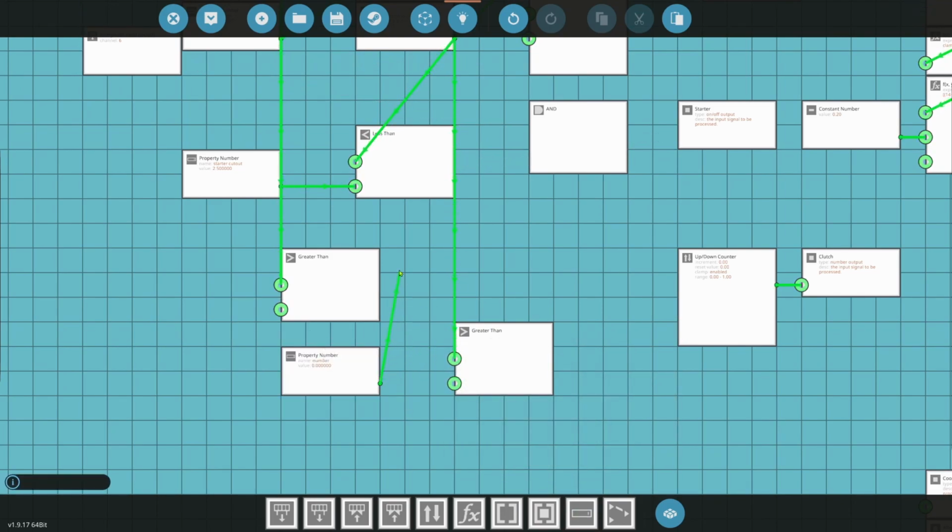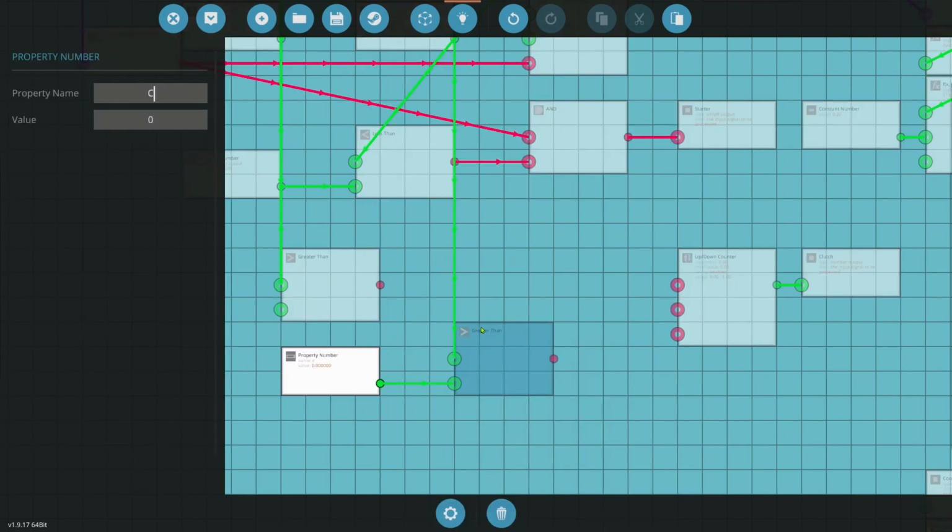And this one will tune in, so we'll plug this in there. Do clutch engagement RPS. I'm trying to make these titles so you know what they're all about. This is the minimum RPS value that we want the clutch to start engaging at. In this case, 3.5 is our idle, and so we'll do if this is greater than 3.5.